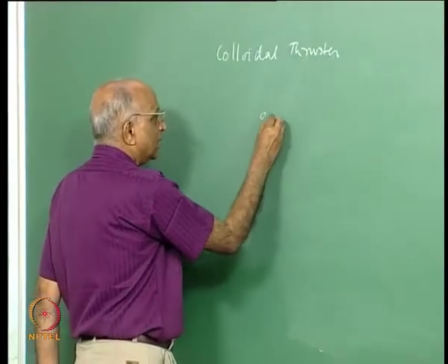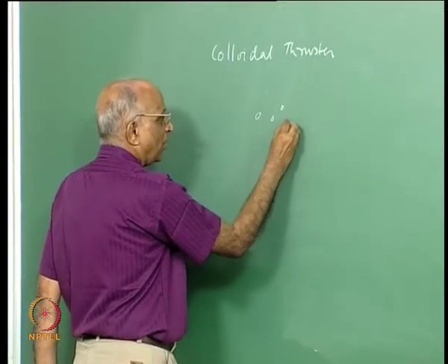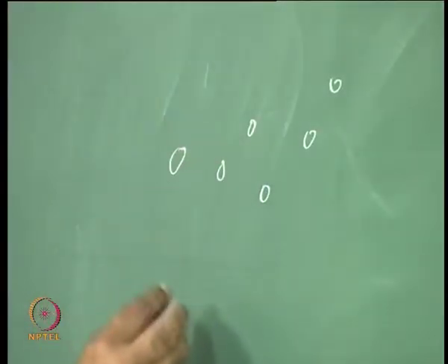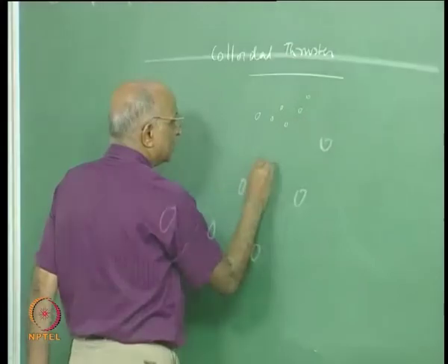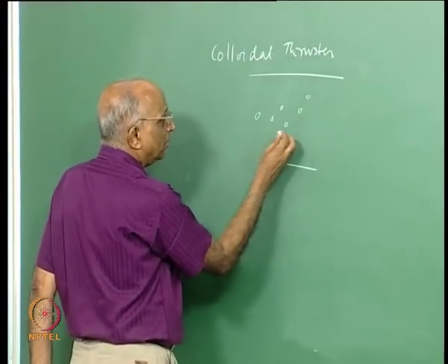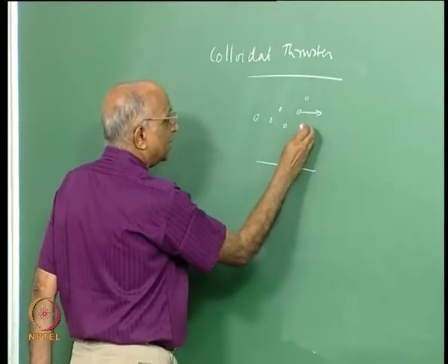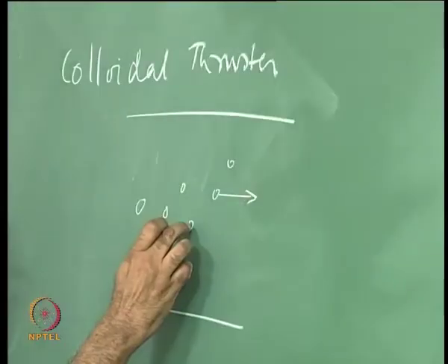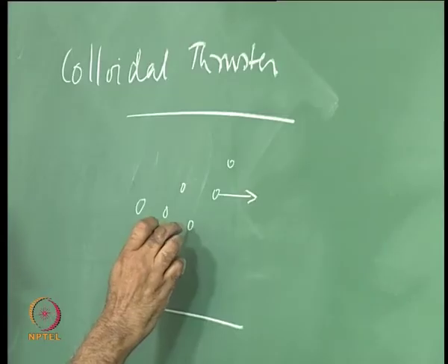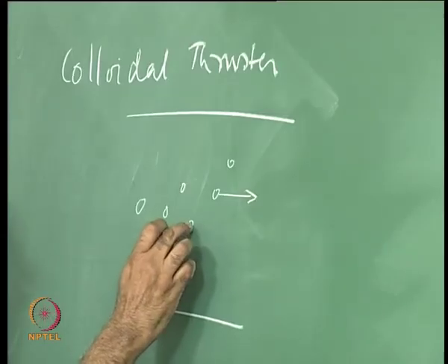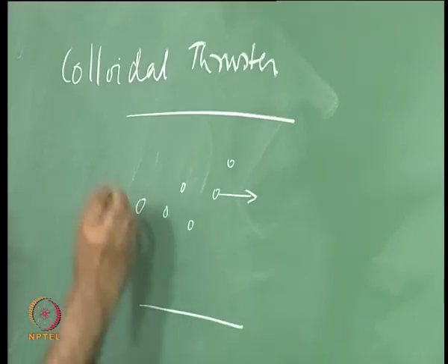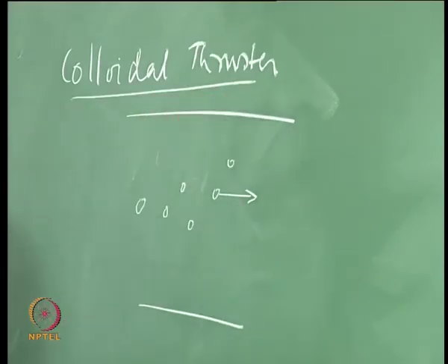These fine particles of dust or droplets, which is something like an aerosol, are charged, and these charged particles, in an electrical field, could be accelerated, and this could be used to provide thrust. Namely, you charge the colloids, and once these colloid particles are charged, you put them in an electrostatic field and you generate thrust, and this is what is known as a colloidal thruster.